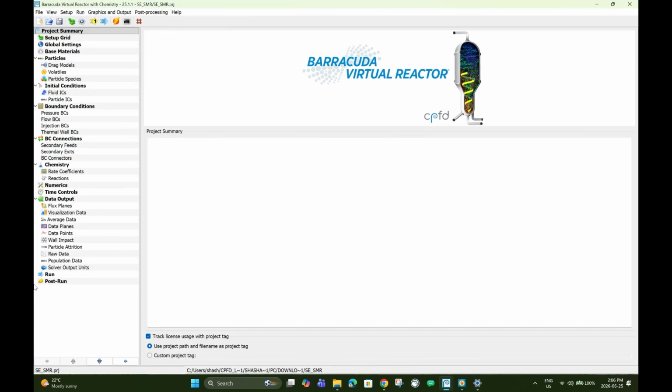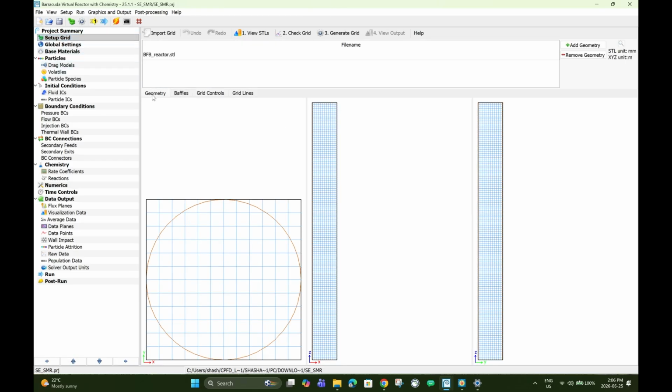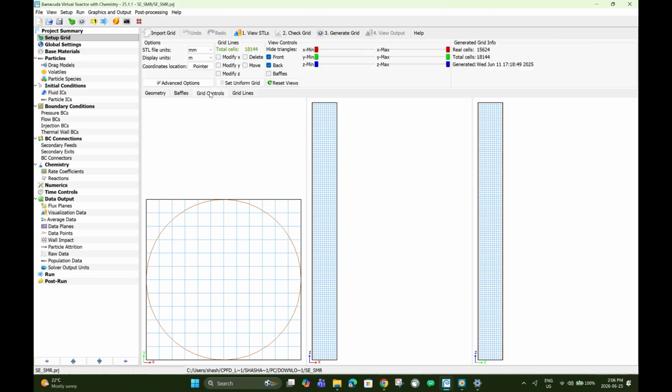Quickly here, let me quickly walk through this. Obviously, more instructions are on the website there. We provide you with an STL file that we set up for this model. Obviously, the grid is generated. One thing you need to do is, because we do not generate these grids when we upload the support files, to keep the file size small, do generate a grid before you run the model.